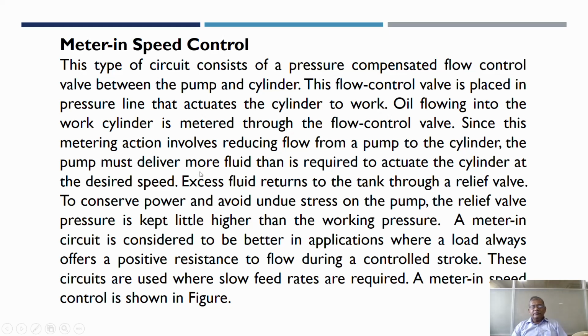the pump must deliver more fluid than is required to actuate the cylinder at the desired speed. Excess fluid returns to the tank through the relief valve. To conserve power and avoid undue stress on the pump, relief valve pressure is kept a little higher than the working pressure.